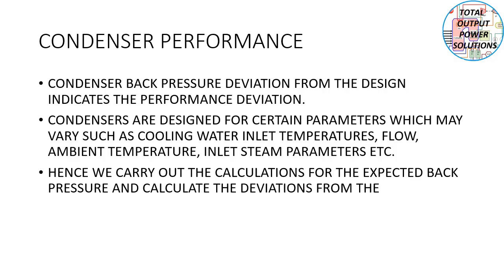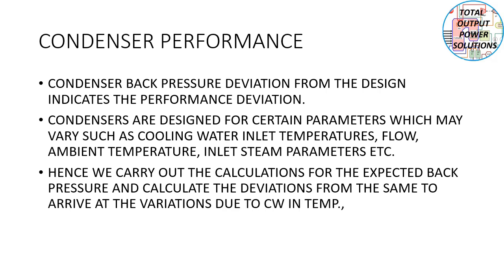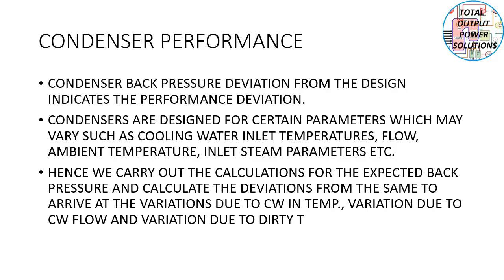Hence we first calculate the expected back pressure and then calculate the deviations from it, to arrive at the variation due to CW inlet temperature, the variation due to CW flow, and the variation due to dirty tubes. So these three things we'll be finding out today.